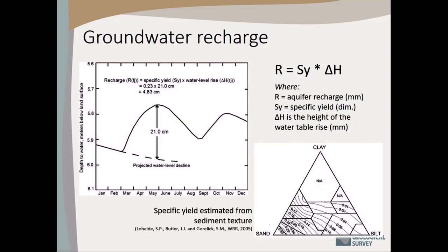Yeah, so this one. Everybody here is familiar with the soil texture classes, so you can tell me a lot about that. So this was work that they did with some modeling efforts, some field verification, to look at what the apparent specific yield is. Not the total; if you do it on a particle size basis and look at soil pores, these values are going to be a lot higher. This is how much of that specific yield is going to change in the short term, like within a day or two.